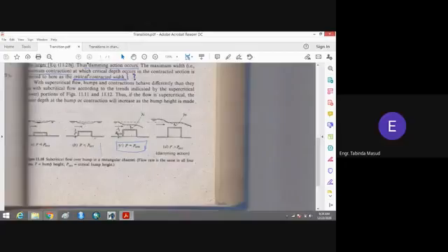Here the depth of the flow is further decreased on the weir, but once it goes from the weir, it again gains its total energy, and has the same depth of the flow as it was at the upstream side. You can see that in both these cases, the depth of the flow at the upstream and downstream is the same.